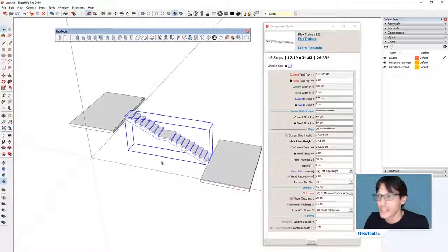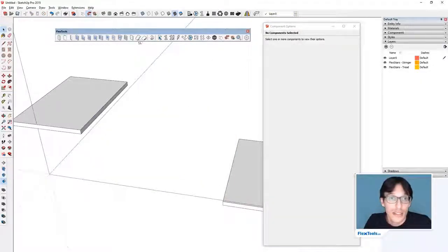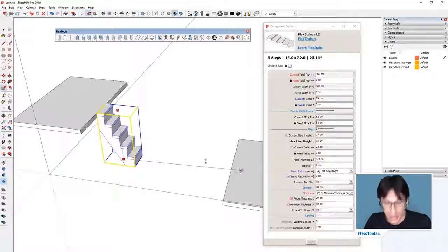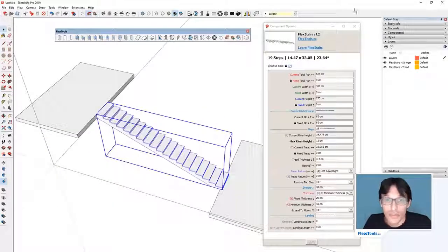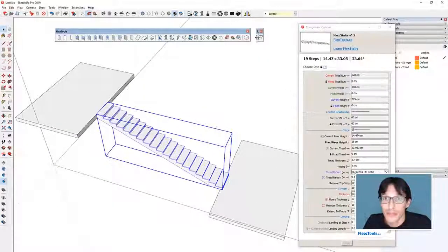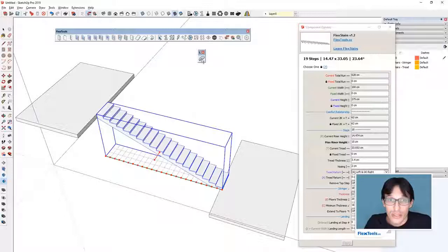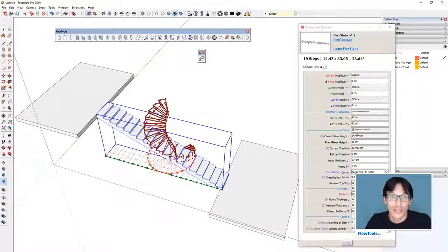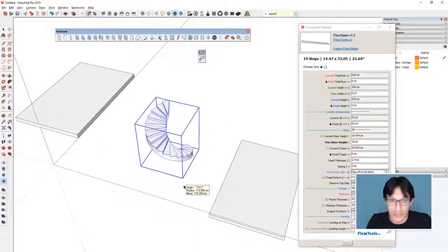If we take the steps over here, hold on, I'll bring a new set of steps. With the power of a very nice plugin by Thom, I'm sure everybody knows him, called TrueBend, you can bend the steps inwards or outwards, and you have spiraling steps pretty quickly.